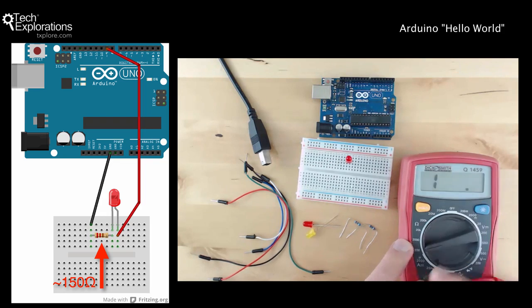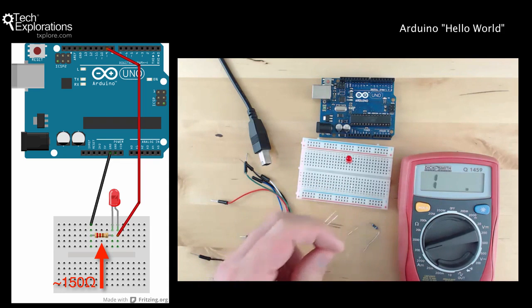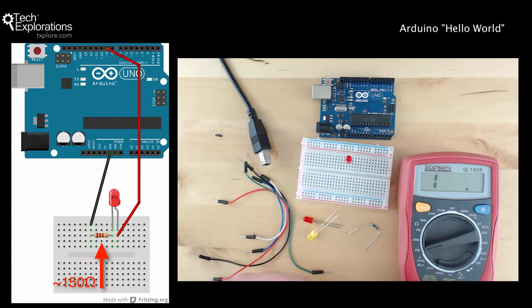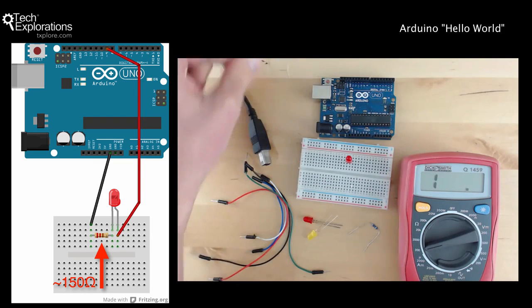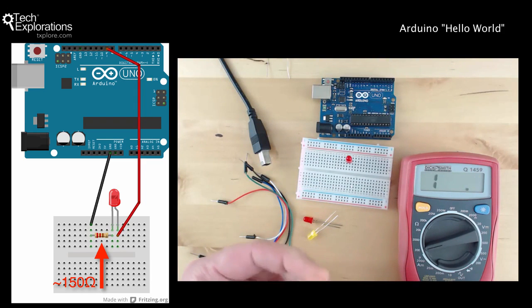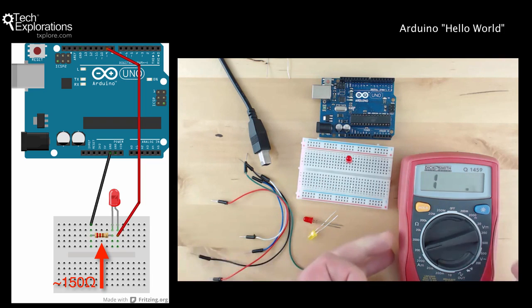I'm going to go for the, say, 200 ohm maximum, because I think those resistors are smaller. So let's check the first one. This one is 68.5 ohms. Might be a little bit on the small side. What about this one here? This one, yeah, 179 point something. That would do a little bit better.